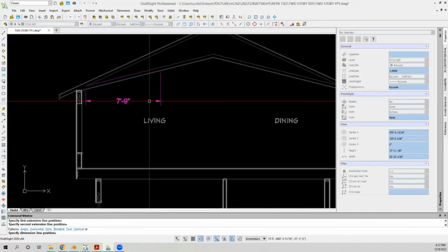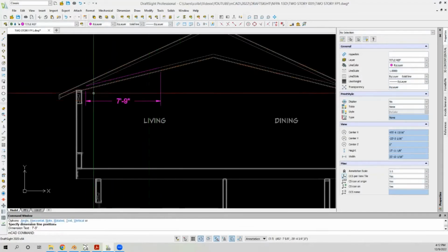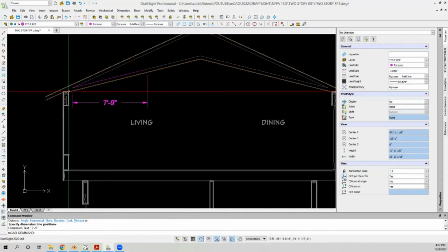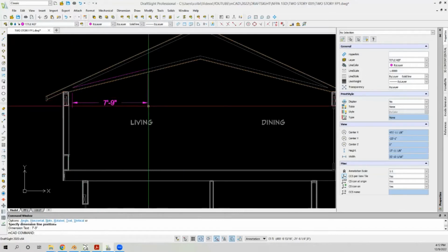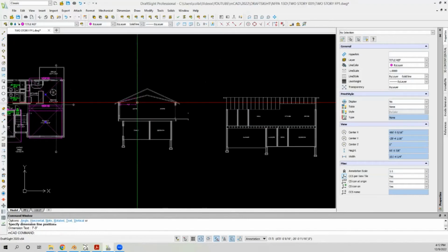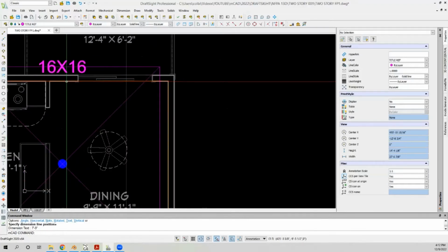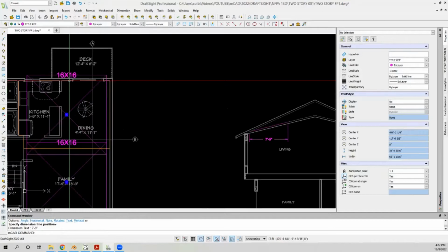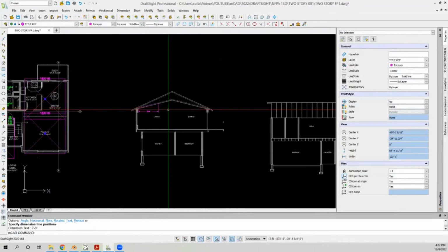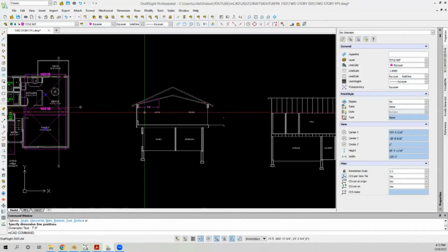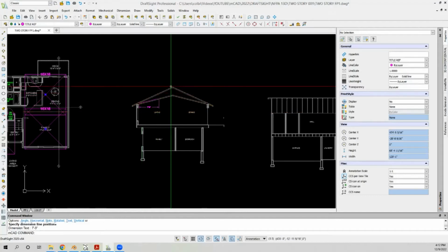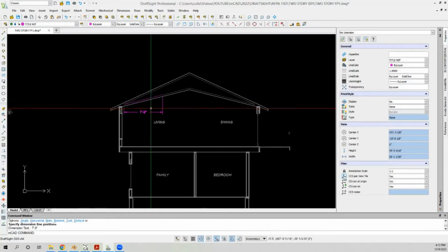And so an 8-foot line on a 3:12 slope like this is only 7'9" horizontally. So we want to make sure that we're no more than 7'9" off of this wall. And then your heads, the spacing between them should be no more than twice that distance. So that would be 14'6".